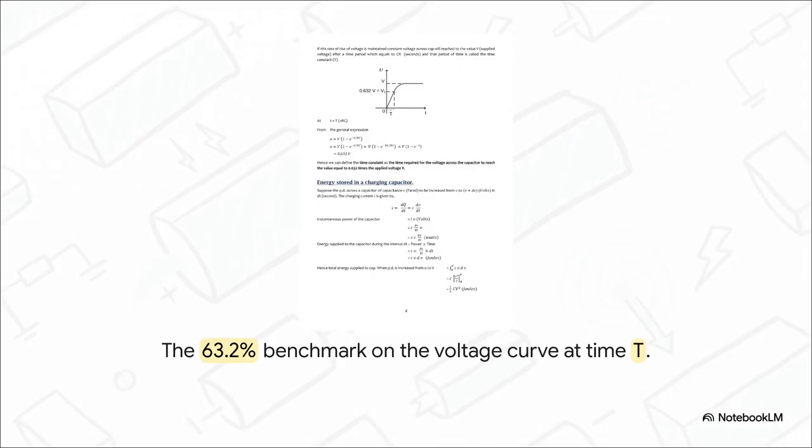Now, what's really interesting about this slide is how we can anchor that 63.2% value directly onto the physical charging curve itself. Think about it. If the initial rate of voltage rise just stayed constant, moving in a perfectly straight diagonal line, it would hit the full supply voltage exactly at time t.